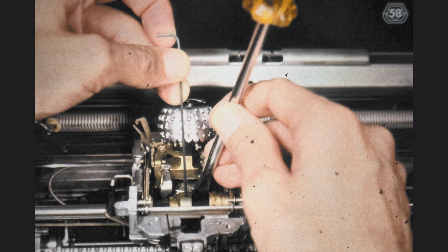Now let us adjust the skirt clearance. You know that the detent cam follower exerts left-to-right pressure on the detent cam. In order to change the position of the cam, it is best to first loosen one of the set screws of the detent cam completely, so that the cam is held in position by only one set screw.